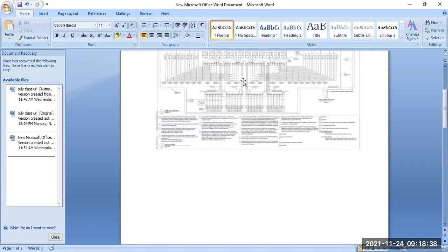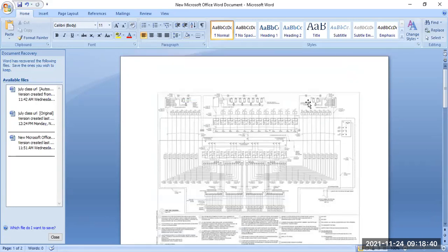So we have to know the panel diagram and study the panel. See, here your valve is showing a fault. You can see 1, 2, 3, 4, 5, 6, the number 6 valve is showing a problem. So you have to know what the other connections are, then go for back checking.